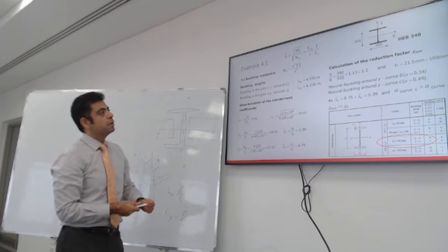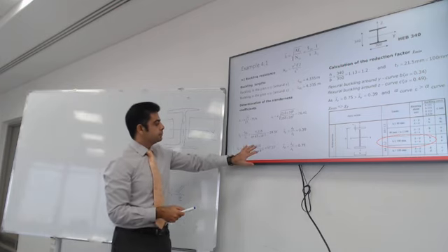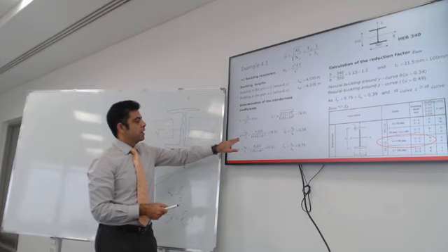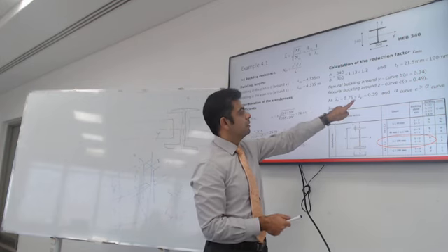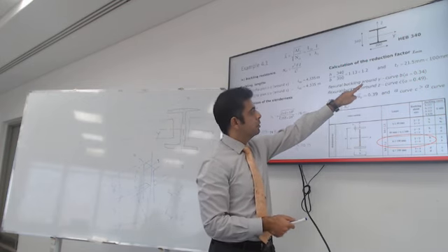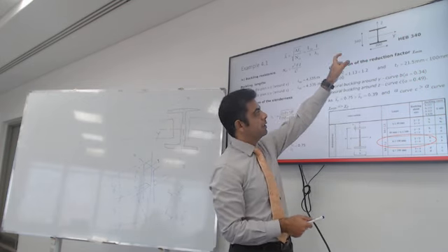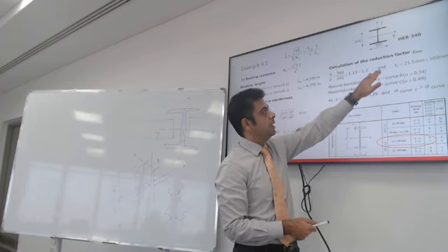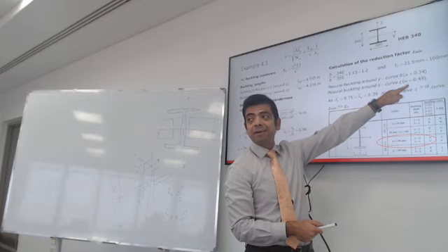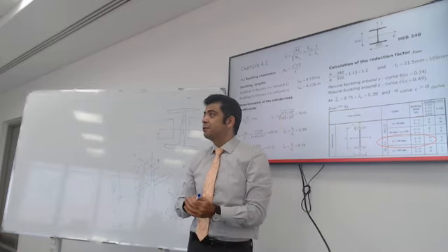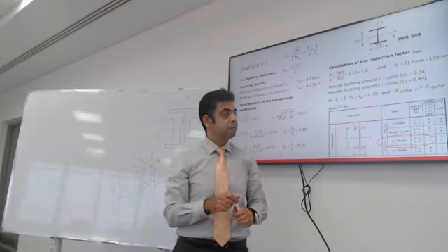All right, so what I did here, I got the slenderness ratio, and then you need to get the curves based on the width and depth of the cross section in order to get the imperfection factor and choose which buckling curve.